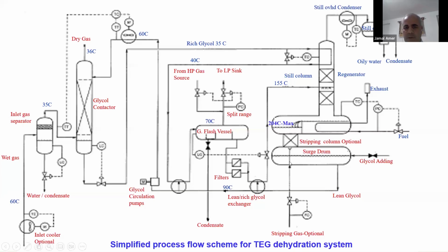Also important here are the filters. We have to keep monitoring the differential pressure across the filters. So with any high differential pressure across this filter, we have to clean this cartridge or replace this cartridge.